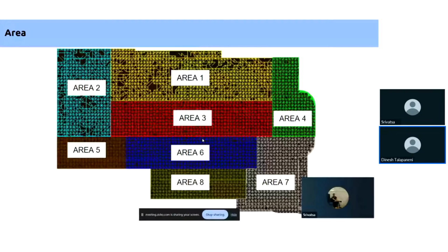What you're seeing in the left side picture is the initial stage of the earthwork. We scanned the entire site even before the work started and gave the exact profile as per the site conditions. When you model based on this profile, you get accurate quantities for execution.